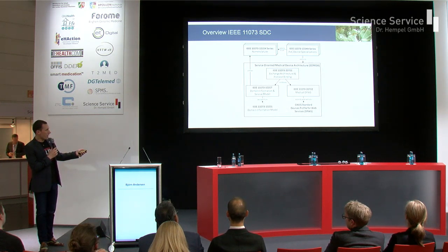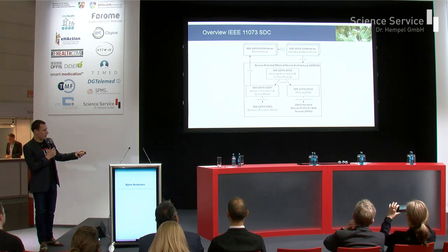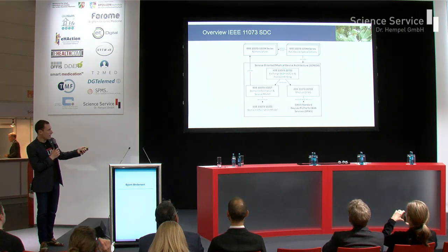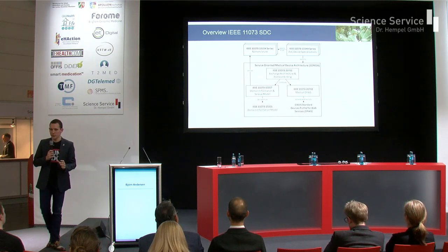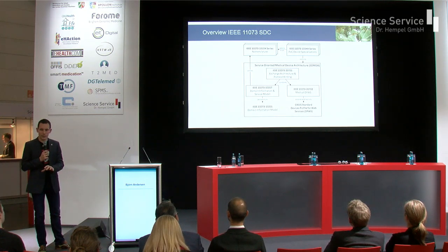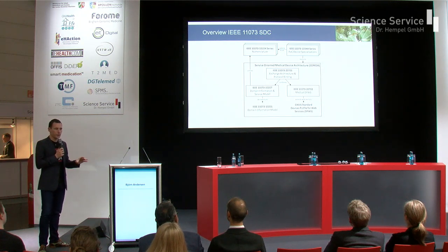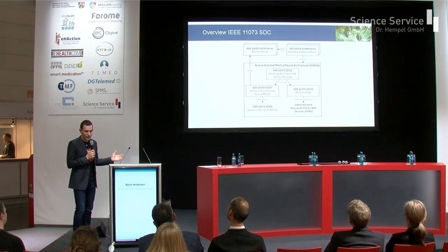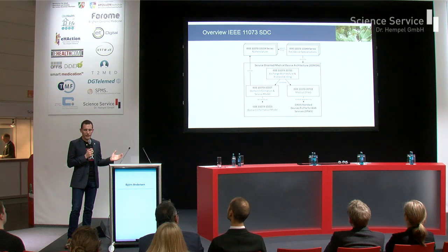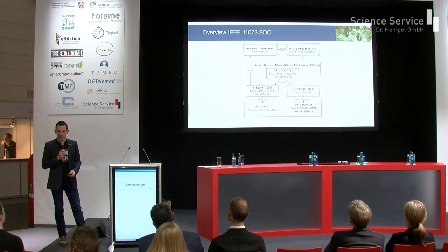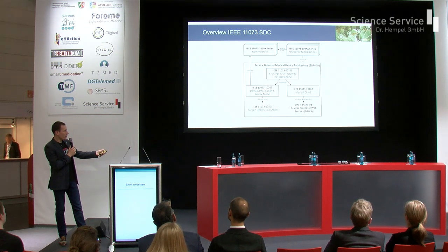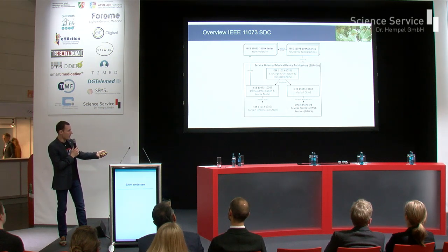Now these two have to go together. You have a model of a device and you have a transport technology, and what we have here is a binding standard. This binding standard tells you which services of the transport technology you need to use in order to transport the messages, the medical device information base that represents your medical device on the network. So whenever you hear those magic three letters, SDC, Service-Oriented Device Connectivity, it usually refers to those three standards.